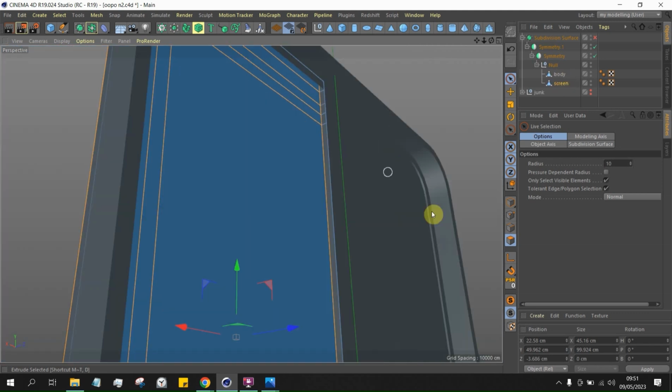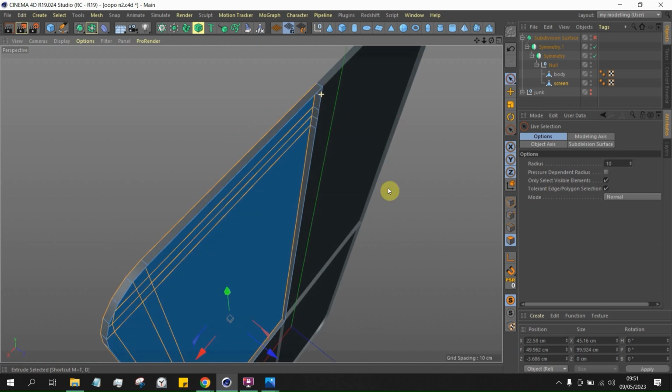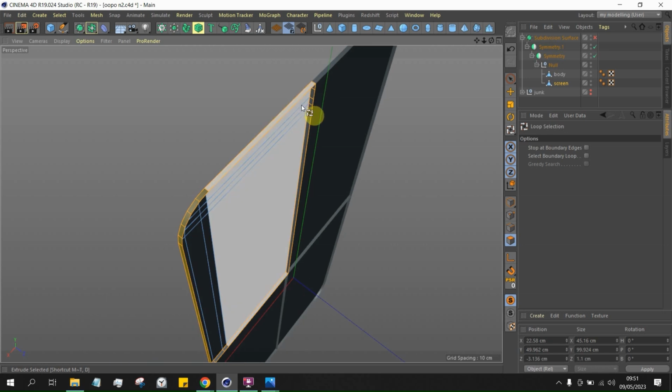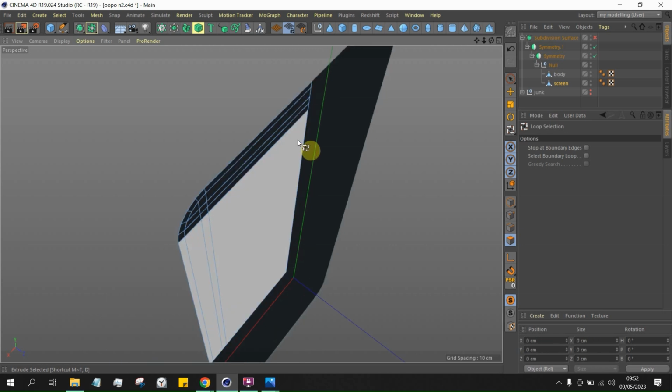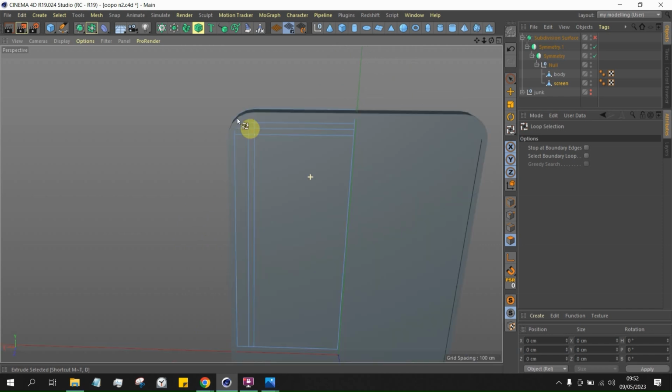Let's see only the screen. Hold this tool and just click it. It's called viewport solo. So use U L, and this is loop selection. Select it and then delete. There might be points lying around, so let's use U O to optimize. Perfect. So let's go back to our view.